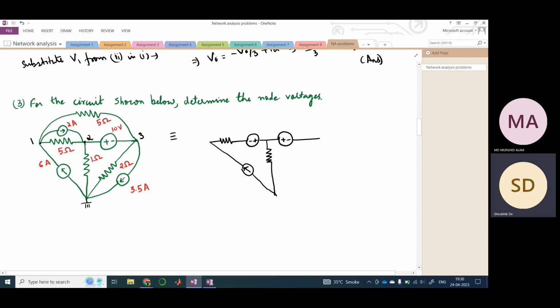And again here we can also apply a source transformation, right? So let us first draw the voltage source. This would be plus and this would be minus, because the current source is pointing from node 3 to the ground node. So this plus would be facing the grounded node here. This would be 7 volts, and again there would be a resistor here.